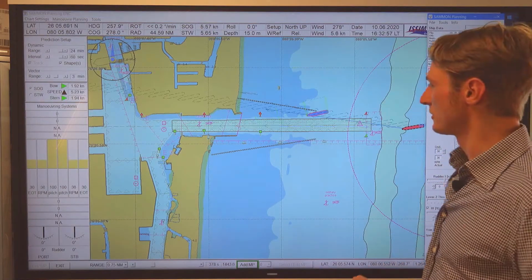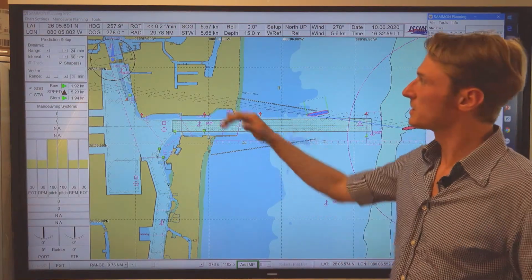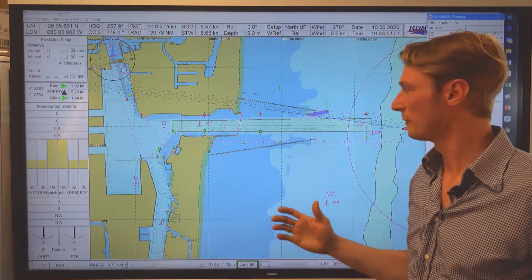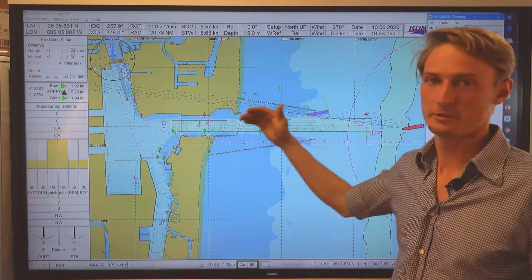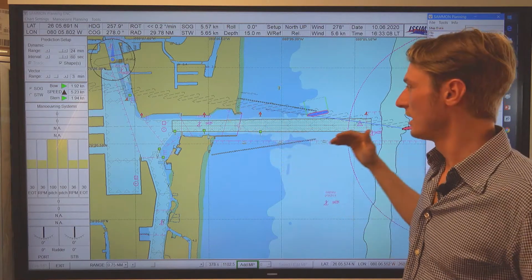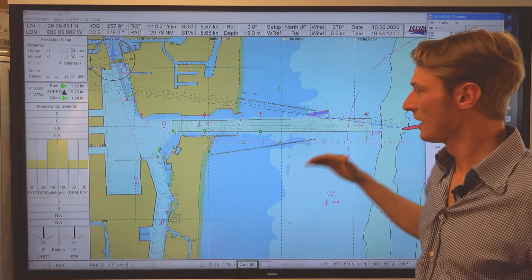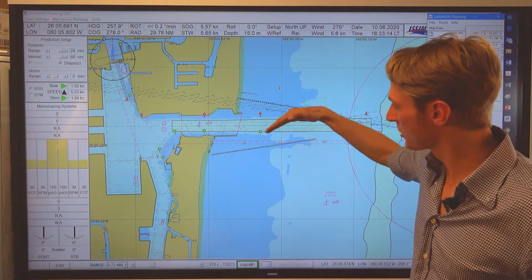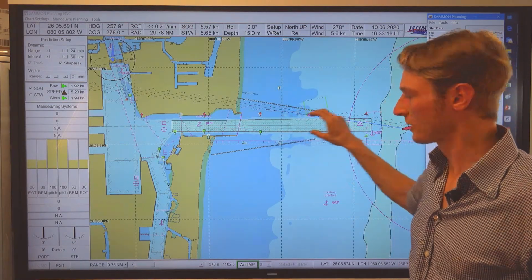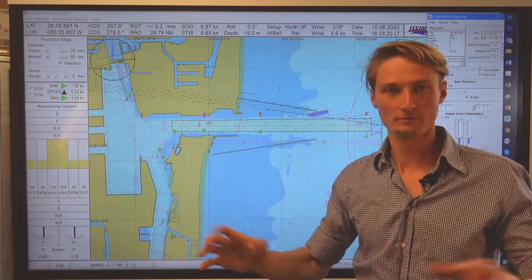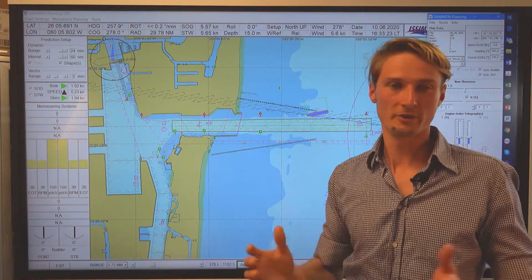Set 3 on both engines. So I decrease my speed. I'm sailing with 5.5 knots compared to the 8.5 before, and we have a way higher drift than before. So in order to compensate for that, we need to steer further to the port side, and we will have a larger crabbing angle or a swept track, of course, in the sea channel, which limits the space on port and starboard side.